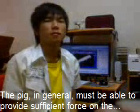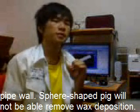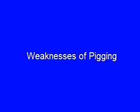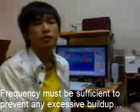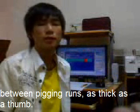The pig in general must be able to provide sufficient force on the pipe wall. A sphere-shaped pig will not be able to remove wax deposition. Frequency must be sufficient to prevent any excessive build-up of wax deposit. An estimated build-up of 1 mm to 4 mm between pigging runs is used as a rule of thumb.